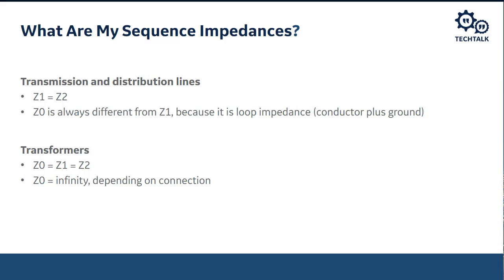At either rate, the reason that we do that is because you're setting the reach of that distance element in positive sequence quantities. When you set a zero sequence quantity or a ground distance element, it needs to know what the ratio of that reach is. And so it's either using a K0 to calculate that, or we're giving that elsewhere as a setting.